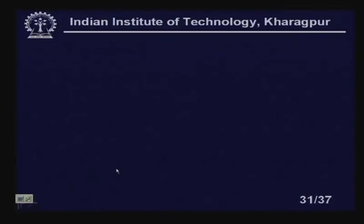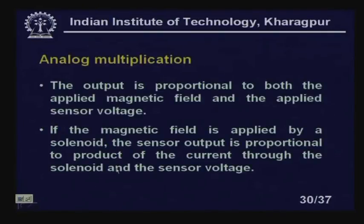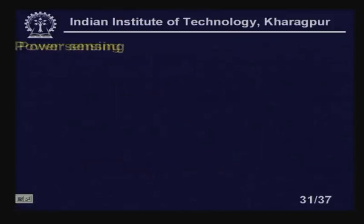Now, let us go back again. The output voltage is proportional to both the applied magnetic field and the applied sensor voltage, right. If the magnetic field is applied by a solenoid, then the sensor output is proportional to the product of the current through the solenoid and the sensor voltage, isn't it? So, using that principle, I am making the analog multiplication.